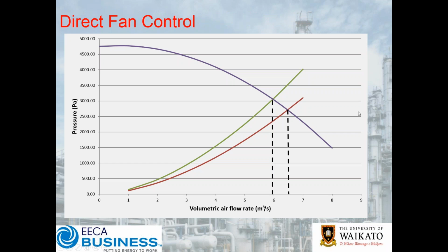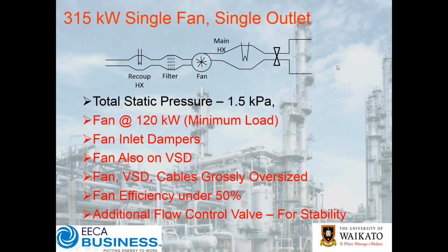So sorry, just to go back here. Once again, when we're playing with our system, the fan might be fixed, but then as we tweak these other dampers on the system, we're obviously, as we've already talked about, going to move up and down that fixed fan curve. Okay, so what we want to do now is work through a couple of very simple examples of how this all translates.